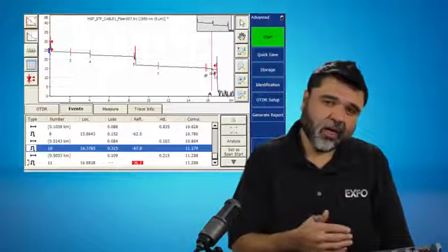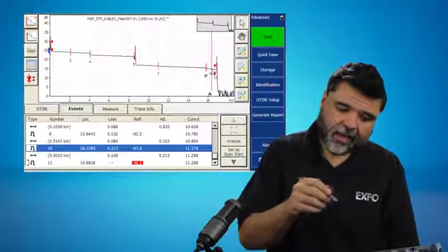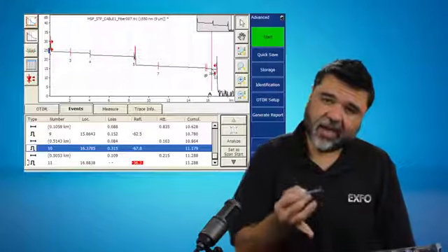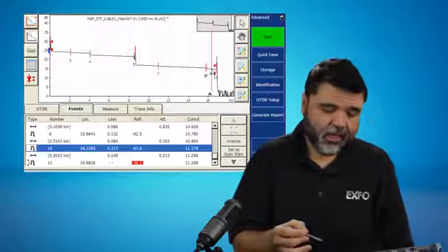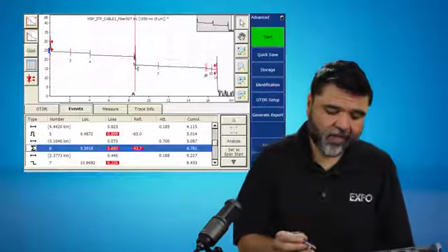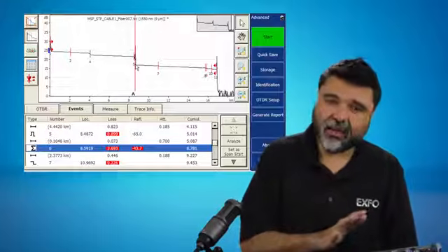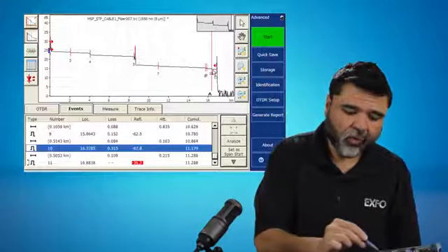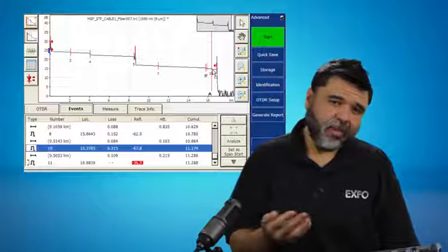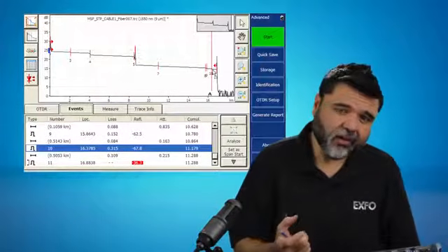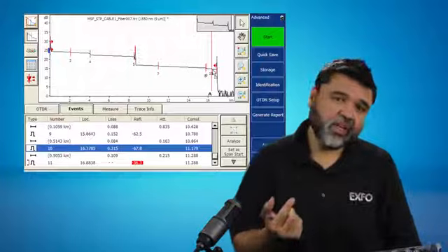In this case here, I shoot an OTDR trace, and I would find the reflective events that have the highest amount of reflection. So in this case here, there's one over here that has minus 43 dB of reflection. I would probably address that connector first for cleanliness than I would this other one at minus 67 dB. And so it's really a great way for you to identify your connectors and which ones are giving you problems.